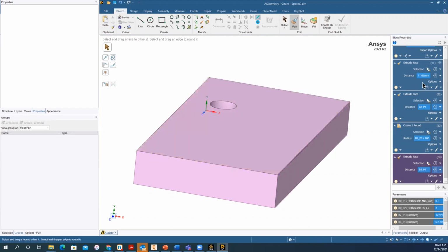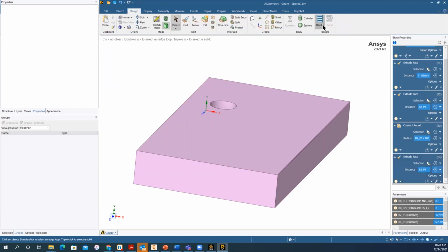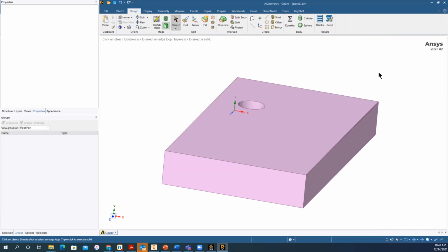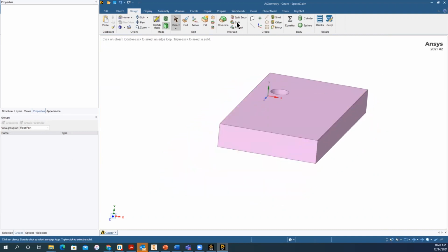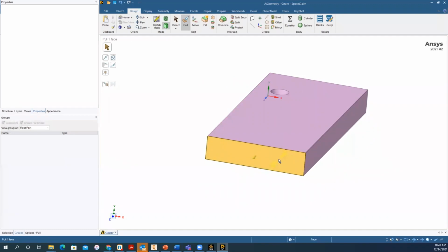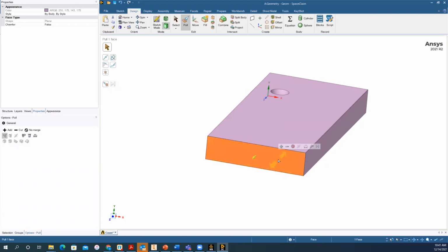Now, if I were to go ahead and quit block recording, then maybe I am able to create a parameter. So I think somebody was asking how to choose the ruler dimension for setting parameters. You select a surface, and while that surface is still selected, you click on this guy over here, and then you select a reference location from where you are measuring that distance. Let me select this guy as the measurement location, and then I can set this as a parameter.